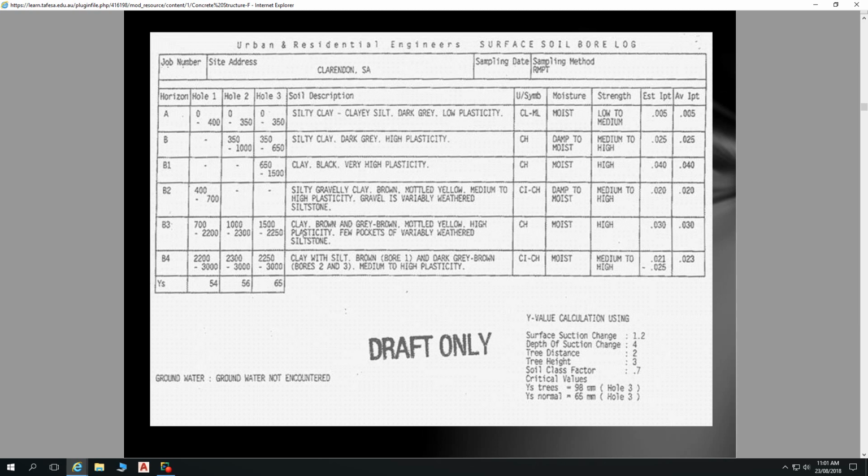So we've got 1, 2, 3 boreholes. It's important that when those samples are taken, the location of our boreholes is accurately recorded, so we can then produce this plan. So typically our borehole location plan, so that bore log has to be read in conjunction with this plan as well. Yes, we can get some information from that separately, but the bore log and the plan assessed together give us more information.